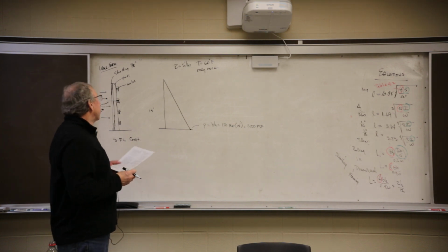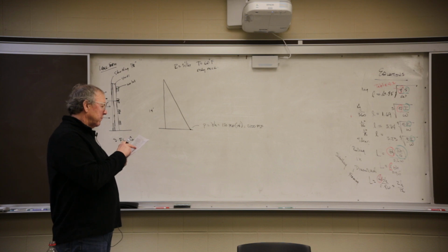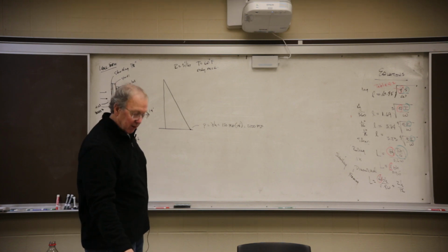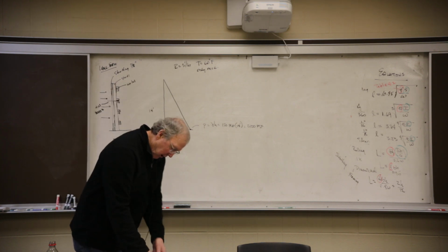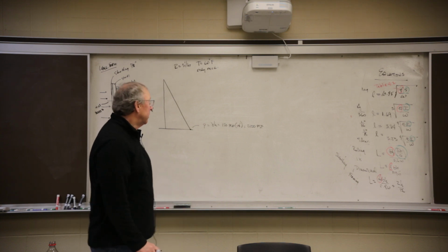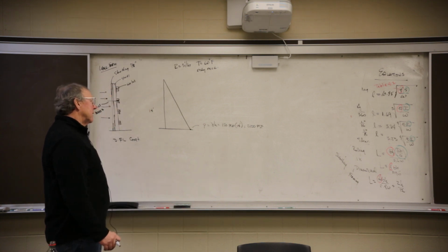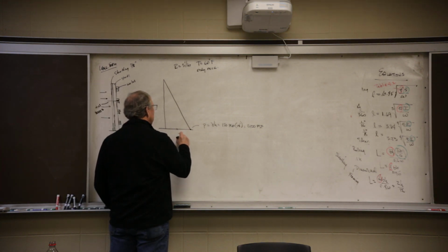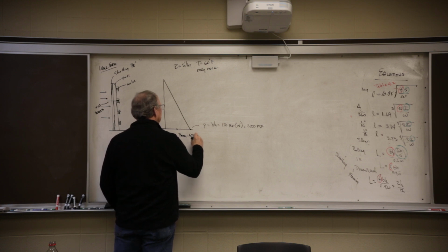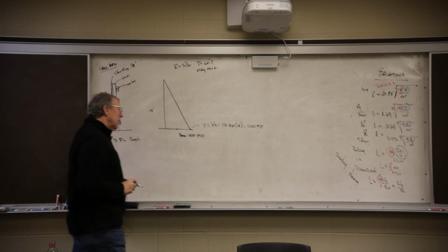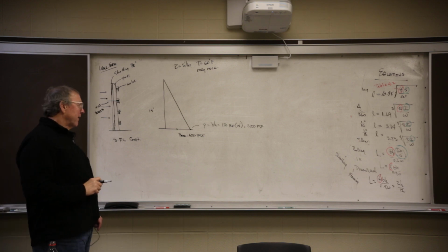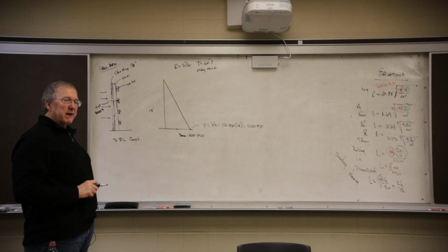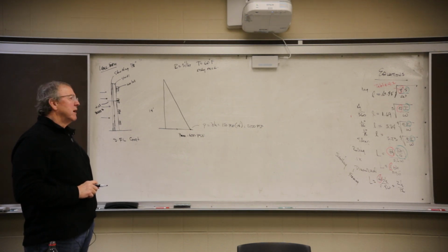So if we look at that, go to 3 feet and 60 degrees. And what do you get? I get 600 pounds per square foot. If you look at your book, that's what they've used. So I'm going to come over here and plot 600. P max equals 600 pounds per square foot. So even though if it was total liquid you would have 2,100 pounds per square foot, with the rate we're pouring and the temperature of the mix, the maximum horizontal pressure is 600.